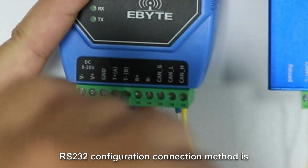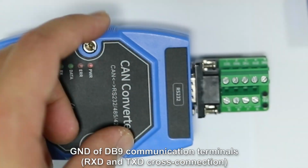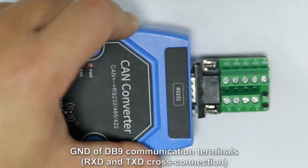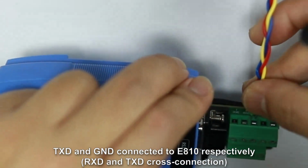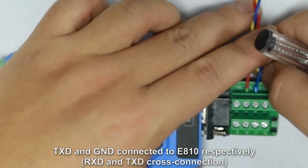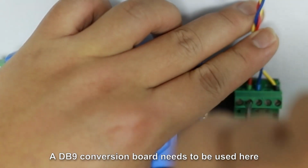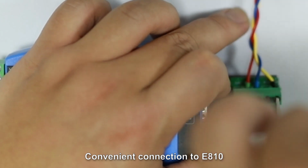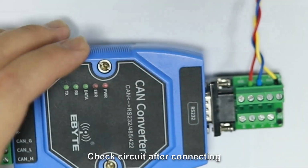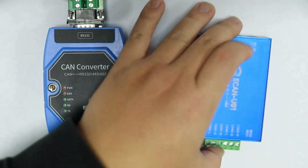The RS232 configuration connection method is: TXD, RXD, GND of the DB9 communication terminals connected to the RXD, TXD, and GND of the E810 respectively. A DB9 conversion board needs to be used here for convenient connection to the E810.